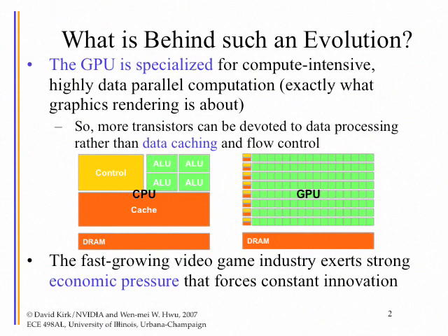And the way to tolerate DRAM latency is not to execute instructions out of order, but rather to have a huge number of threads that can execute on these function units. If one of the threads is trying to access DRAM, you look at these other threads and see if they're ready for execution on the function units.